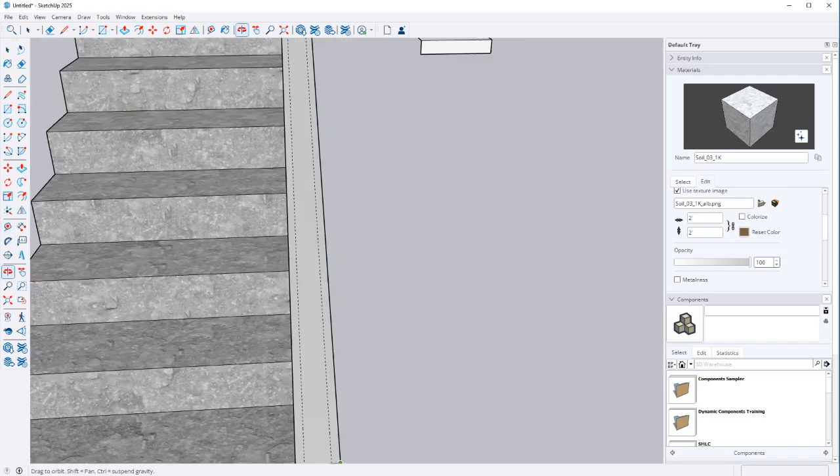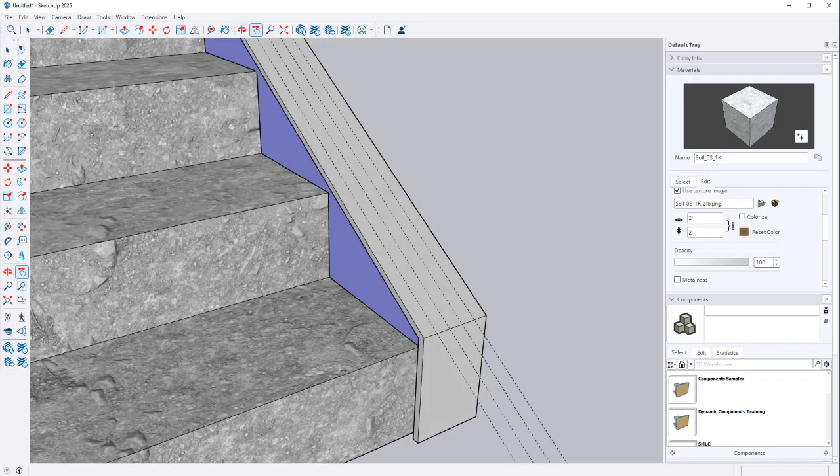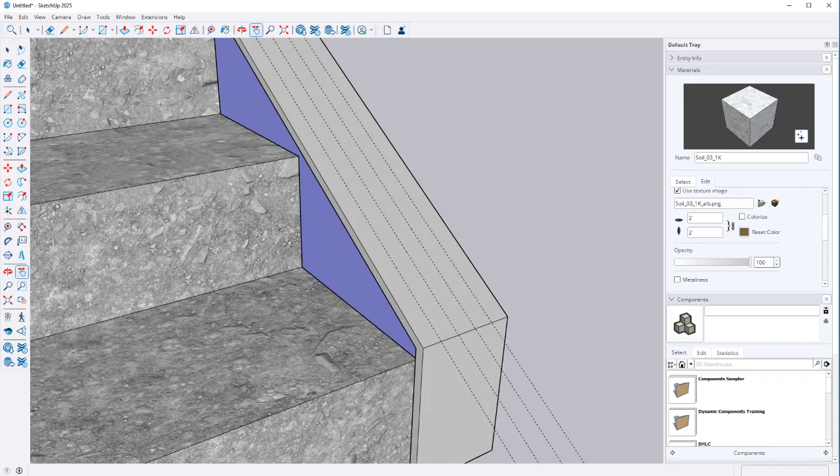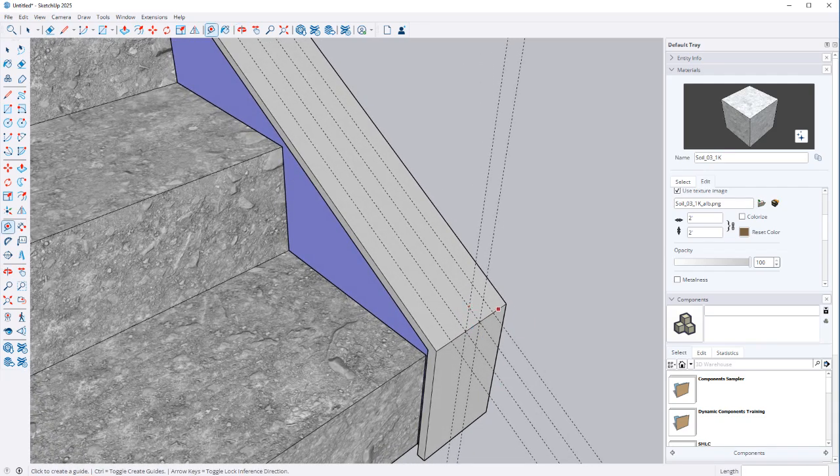Don't quote me on this part because I don't recall the code for some of this off the top of my head. But there's a certain gap, I think it's 5 or 6 inches, that you can't have space between railings, and that's to prevent little kids from sticking their heads inside and getting stuck or crawling through entirely. So we'll go ahead and make this up here.